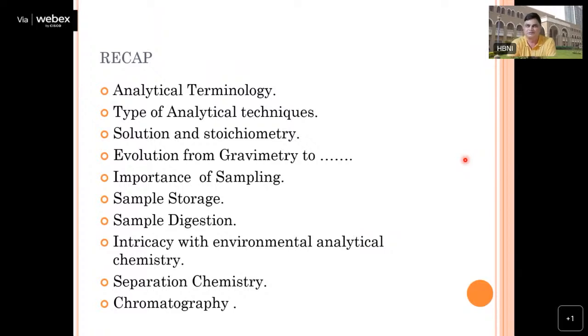and then the sensitivity. Sensitivity is nothing but the slope of the calibration curve. Basically, whenever you are doing any calibration, there is a measurement on the x and y axes. If there is a small change in the x axis, what change will come in the y axis? That will be quantified as the slope of the calibration curve.